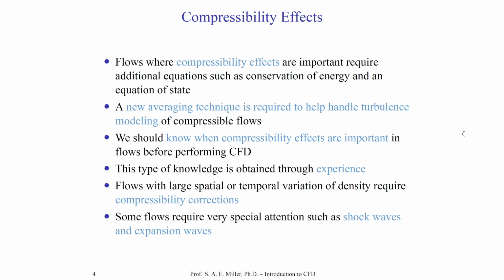The reason I've written this little note here is because you could have a very low Mach number flow, but it might have very large variations of density. Therefore, we would also need to have some sort of compressibility accounted for in the equations of motion and the solver. Now, particular flows that contain shock waves and expansion waves, which are by definition supersonic, require even more additional attention.